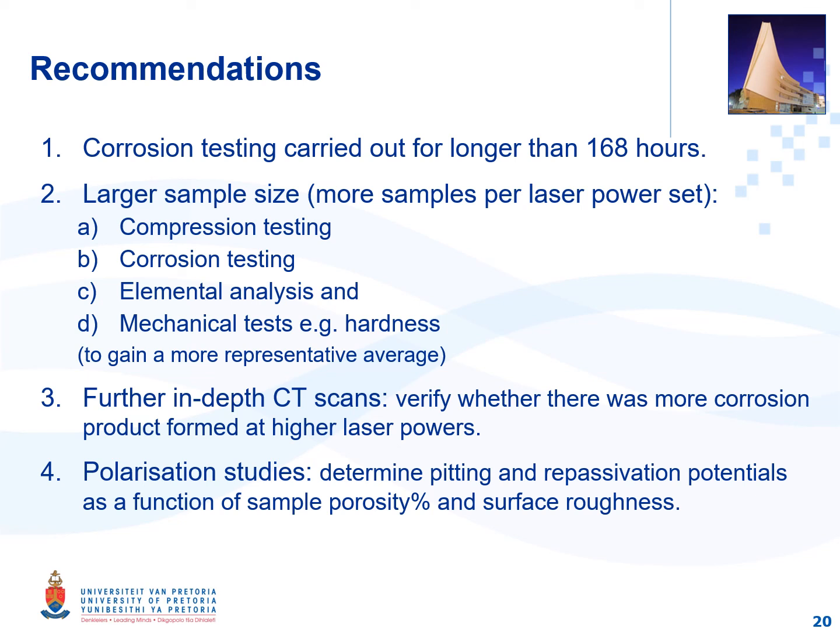Further in-depth CT scans are performed to verify whether there was more corrosion product formed at higher laser powers, and polarization studies to determine pitting and repassivation potentials as a function of sample porosity percentage and surface roughness. This is so that it can be determined when in the corrosion test pitting is expected to occur and when the passivation takes over.